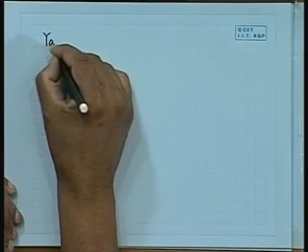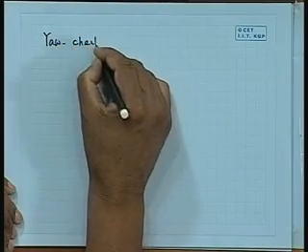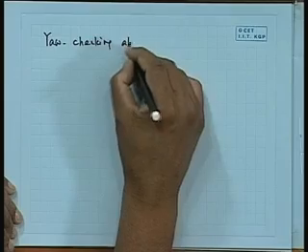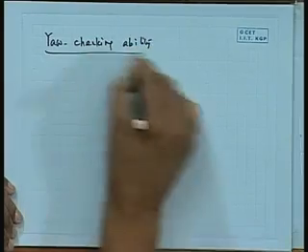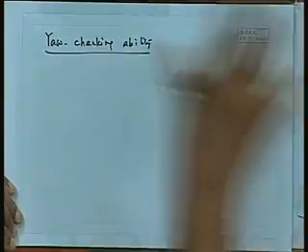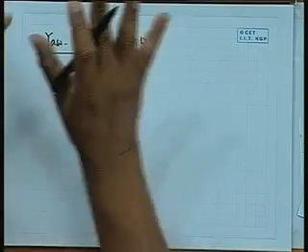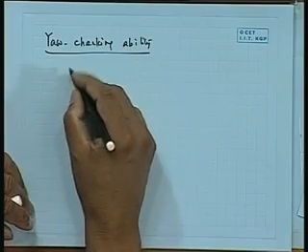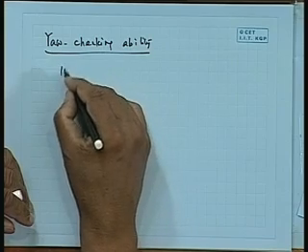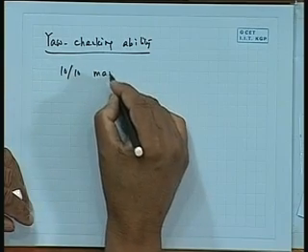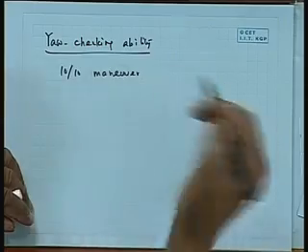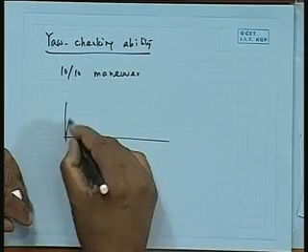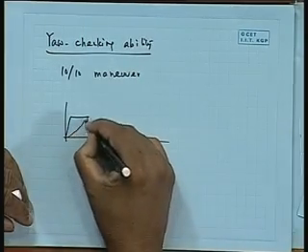Actually, for zigzag, it is called yaw checking ability. See, these two that I mentioned earlier, turning ability, are both outputs or results from the turning circle maneuver. Yaw checking ability is basically coming from the zigzag maneuver. It says here that for a 10-10 maneuver, I am again writing this, the zigzag maneuver. See this 10-10 maneuver.